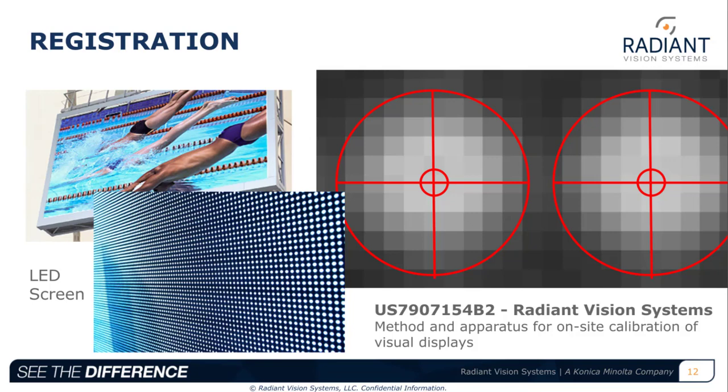For cell phone production, we don't have several nights to correct one display. We have seconds. So we cannot measure the display in many sections. Instead, we must measure extremely high-resolution emissive displays in one measurement. We don't have the luxury of so many sensor pixels per display pixel.